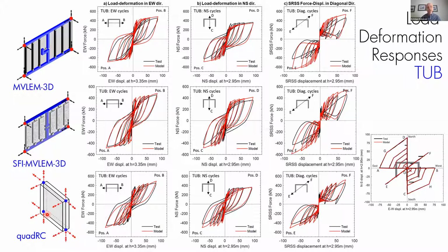finite element model that actually is not based on the plane sections remain plane, and it allows nonlinear distribution of strains along the base. So that's the catch, right? The model formulation. So something to keep in mind. This is true for any plane section model, including Perform 3D or any other model.